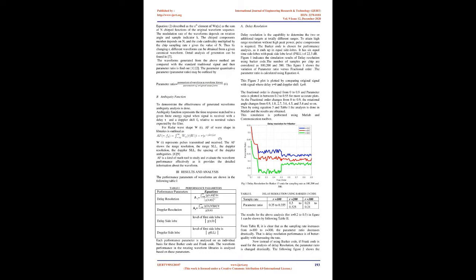If there are n samples of the original waveform, e.g. the traditional Barker 13 code, then C equals C1, C2, ..., Cn is the vector of n samples. The resulting waveform Wa can be defined as the FRFT of the a-th order. Different fractional order x corresponds to different angle as a equals x times pi/2, and different waveforms consist of different angles a. Therefore a fractional waveform library, called the rotating waveform library, can be defined as W equals Wa1(u), Wa2(u), ..., WaL(u), where x equals 0, 1, ..., L represents the total number of waveforms in the library. L depends on different parameters such as the original waveform used, applications of the waveform, and waveform reuse.